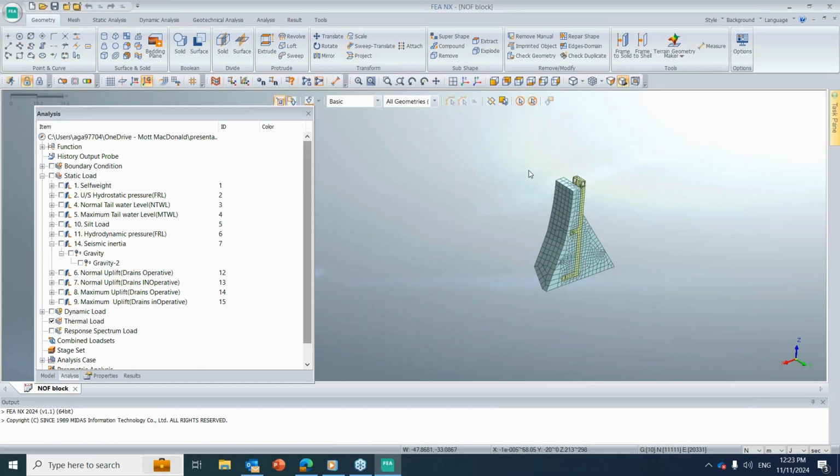We don't provide reinforcement on the upstream face. Yes, around the galleries and in flexural components like lift wells and staircases, reinforcement is required, designed for bending moment and shear forces. In a concrete gravity dam, reinforcement is not provided. Tensions are limited for various operating conditions, and there are various limits provided in the code. We have to abide by that, so that no tension arises and no reinforcement is required. If it exceeds the limits and we can't increase the section of the dam, sometimes we have to provide it in the foundation and on the upstream face, but normally it is not provided.